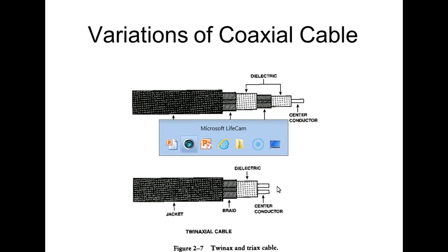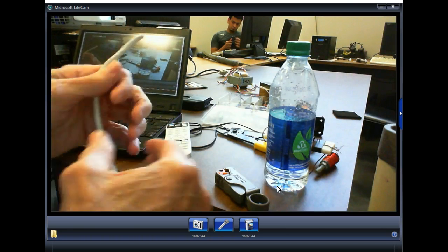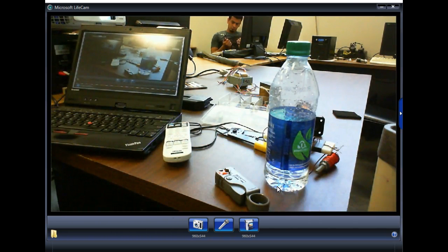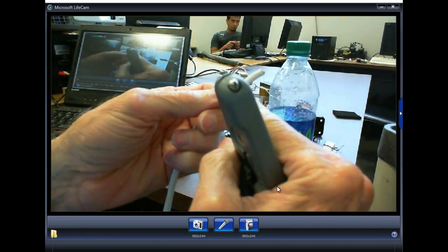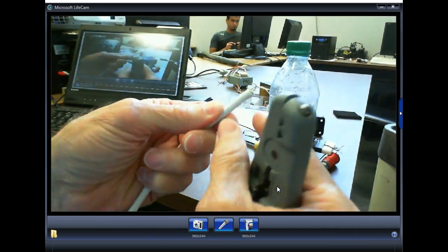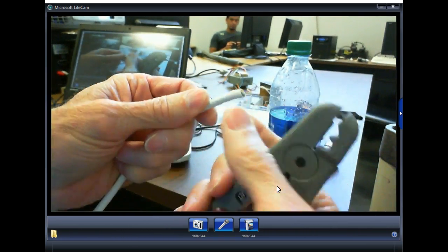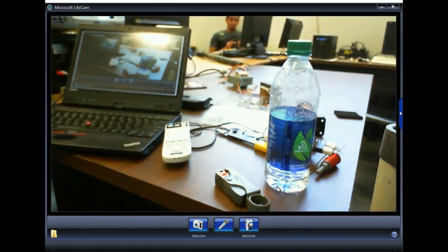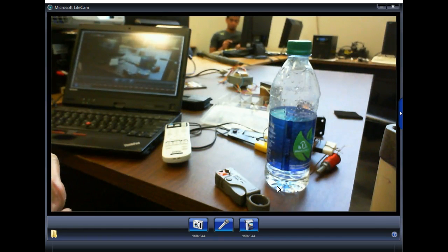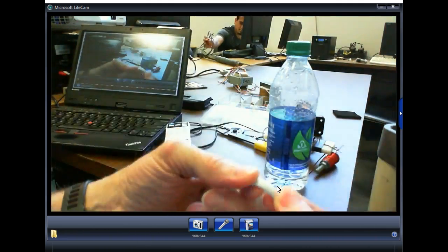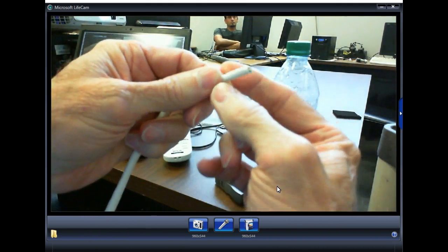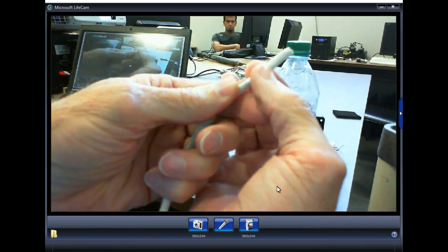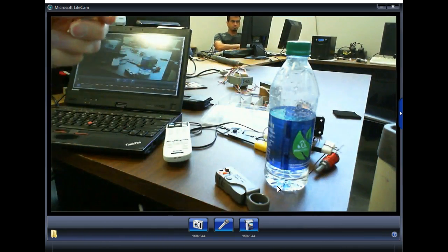A lot of our communication cables use what we call twisted pair. And of course, you've got to be real careful. A lot of people try to strip these with a pocket knife, and they put that thing across here, and instead of scribing it, they try to cut through. If you use a pocket knife, you need to scribe the jacket, right? And then when you scribe it, bend it and break it. Don't cut through the jacket and actually hit one of your conductors.